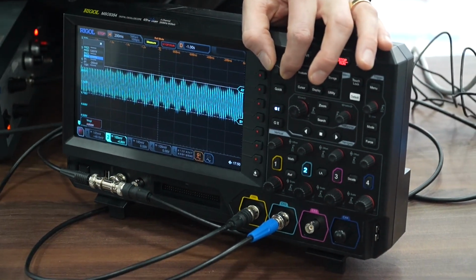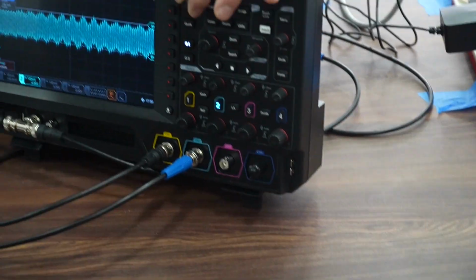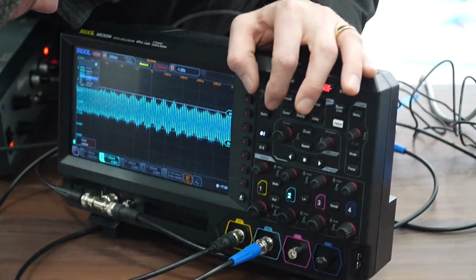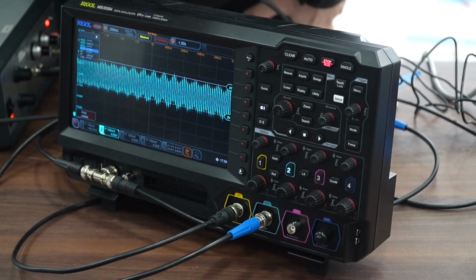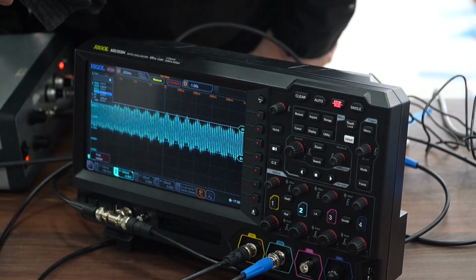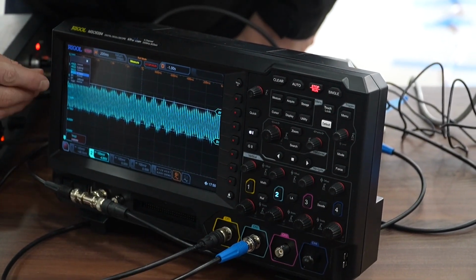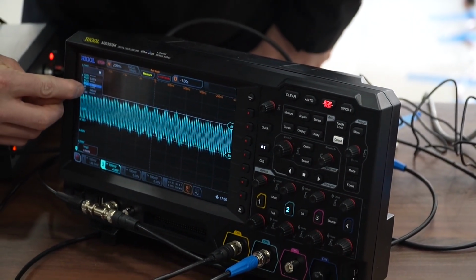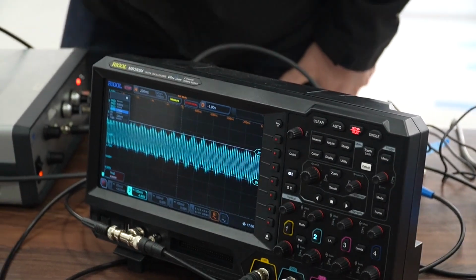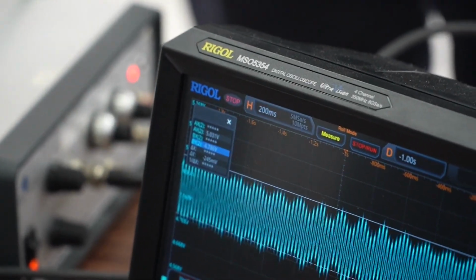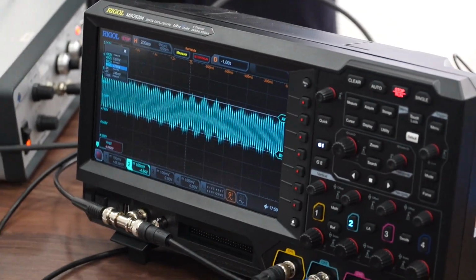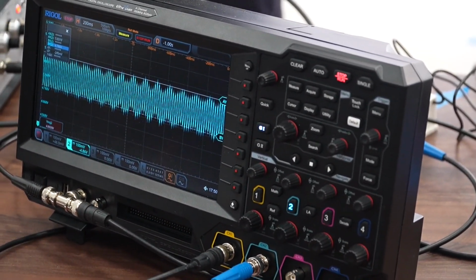And now the lower one I place on the same tips like this. Okay? And now you've got two values. And you've got the difference. And the difference is 245 millivolts, right? This is 2 times the tip deflection. So if you divide that by half, you've got the tip deflection, right?